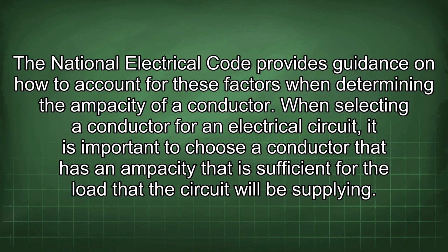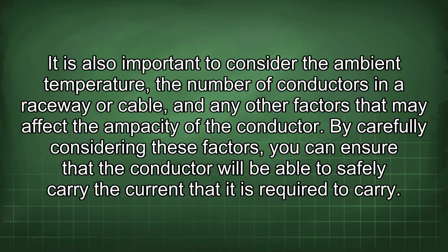When selecting a conductor for an electrical circuit, it is important to choose a conductor that has an ampacity that is sufficient for the load that the circuit will be supplying. It is also important to consider the ambient temperature, the number of conductors in a raceway or cable, and any other factors that may affect the ampacity of the conductor. By carefully considering these factors, you can ensure that the conductor will be able to safely carry the current that it is required to carry.